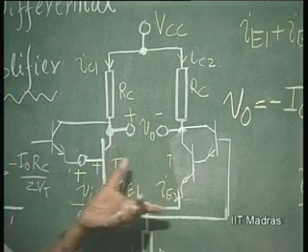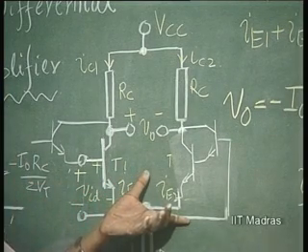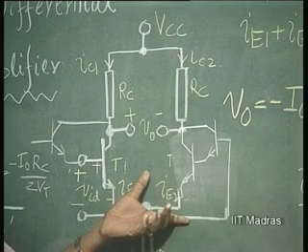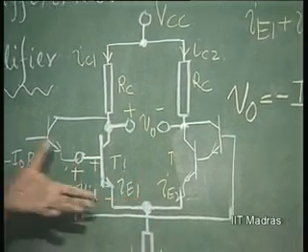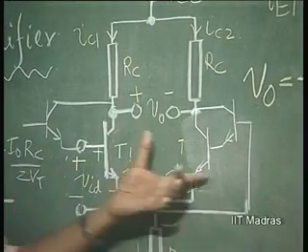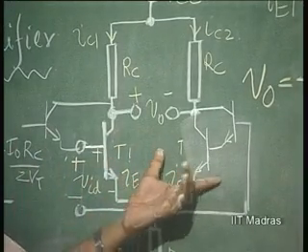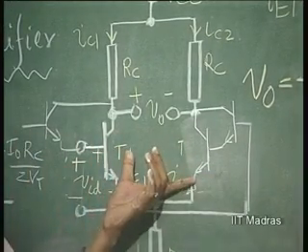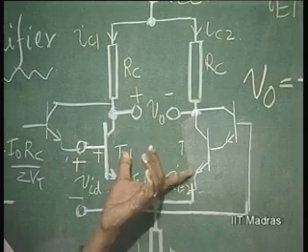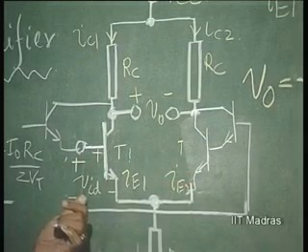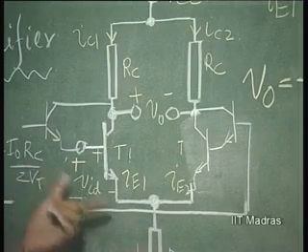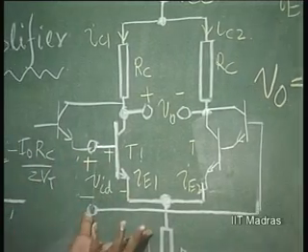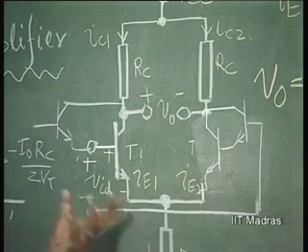Now, there are two pairs coming into the picture, so the uncertainty will be double, right. So, it will be 2 to 4 millivolts. Using more pairs of transistors will result in more input offset, okay. Even though you might put this in to improve the beta of the transistor, you will degrade the transistor differential amplifier in terms of its input offset.